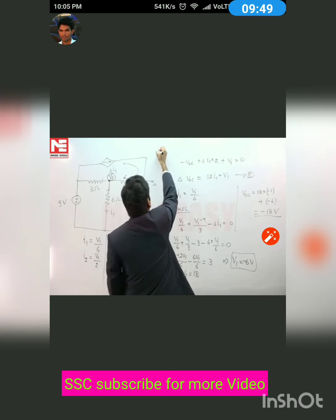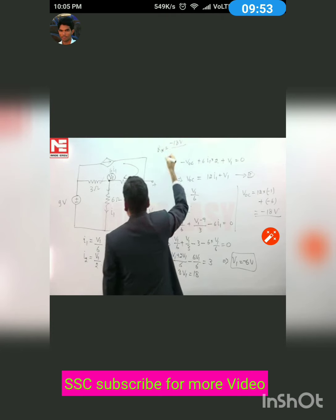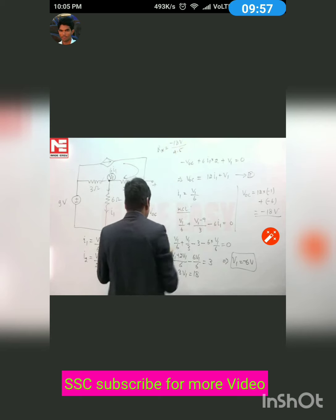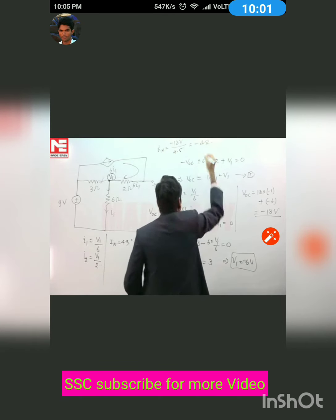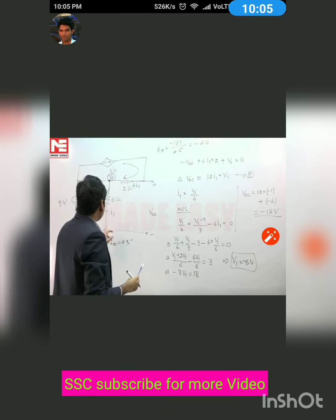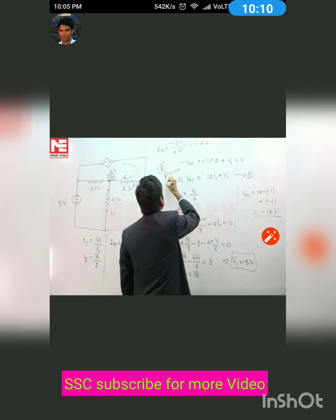Now R Norton can be calculated as VOC, minus 18 volt, upon IN, 4.5. So this comes out to be equal to minus 4 ohm. So Norton's current will be 4.5 ampere and Norton's resistance is minus 4 ohm, which is given in option B. So answer for this question is B.